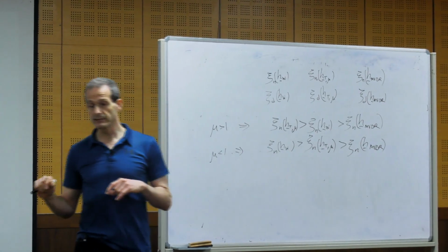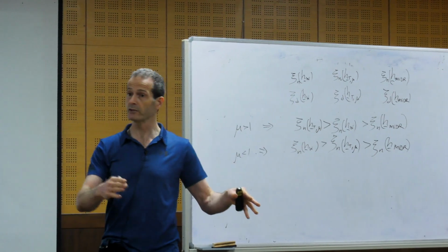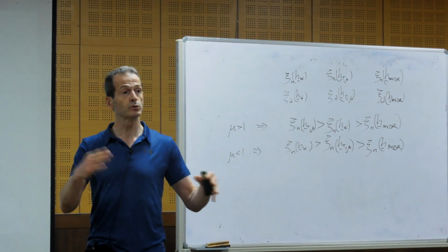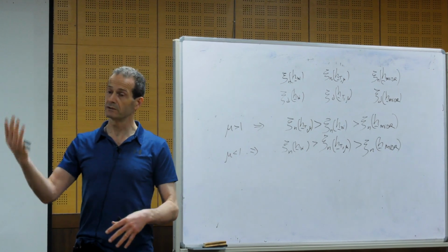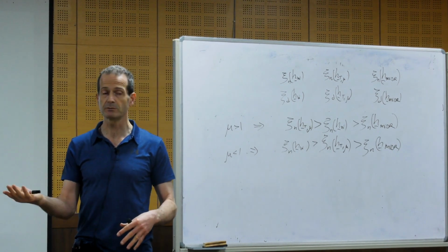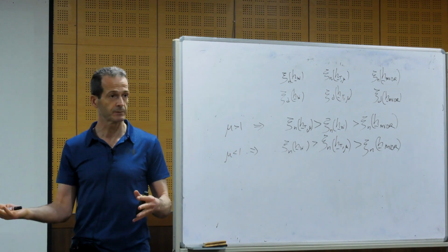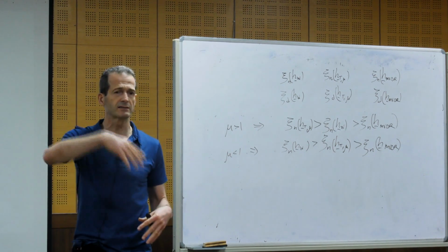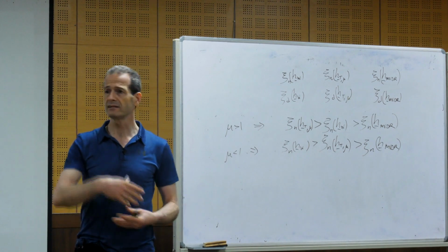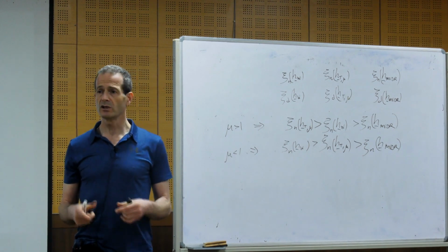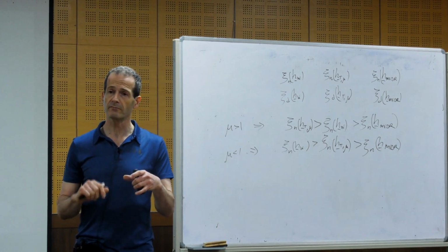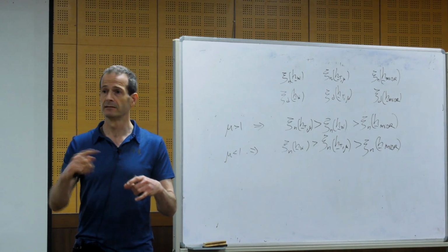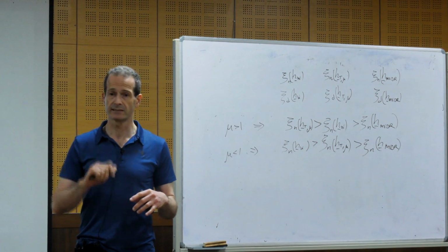Now my question is, do we have to do it in the Fourier transform? Or what is the signal subspace? Sometimes we call it, instead of signal subspace, the signal-plus-noise subspace. But the noise we assume is full rank. It's all over. So we say the signal subspace contains some noise. And the noise subspace is without any desired signal.